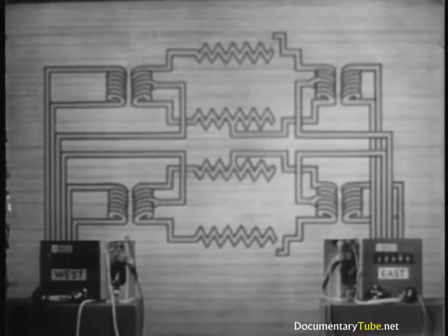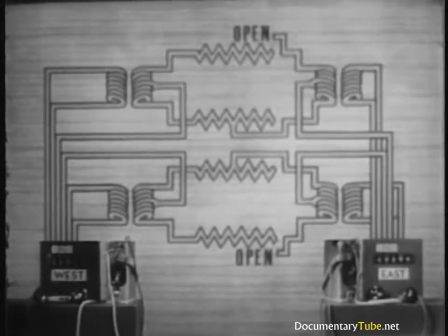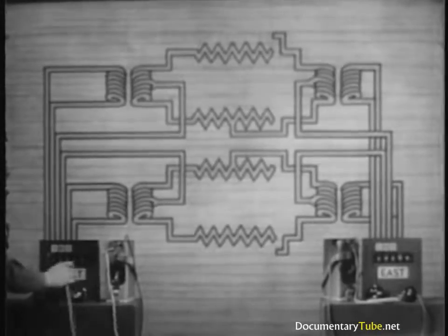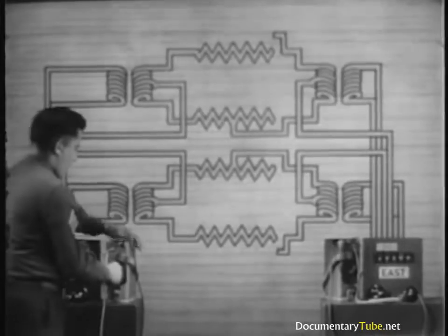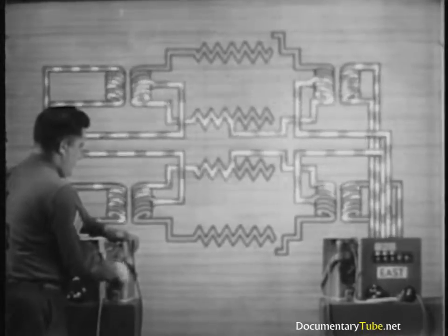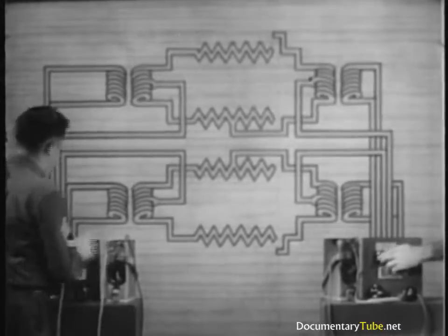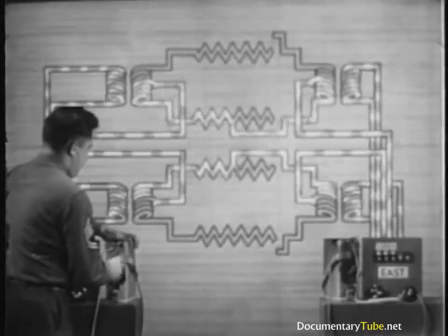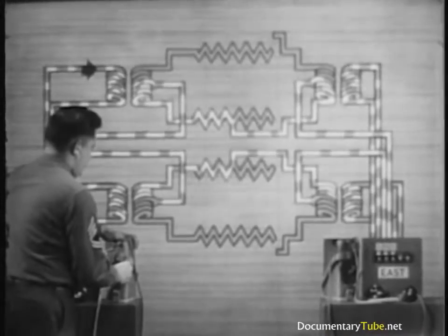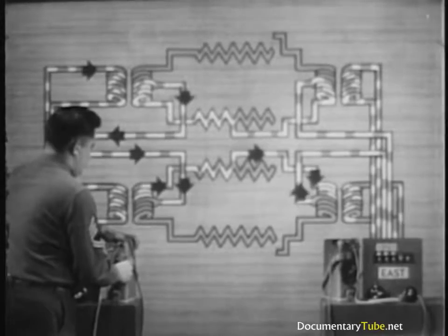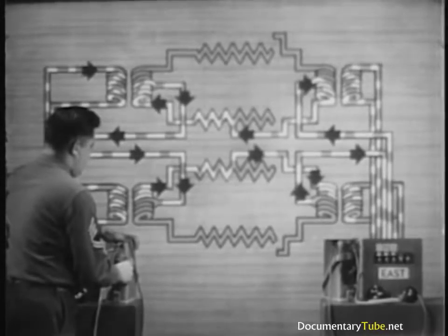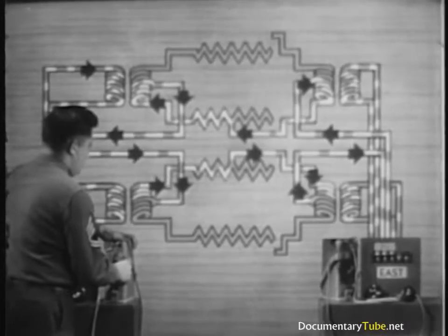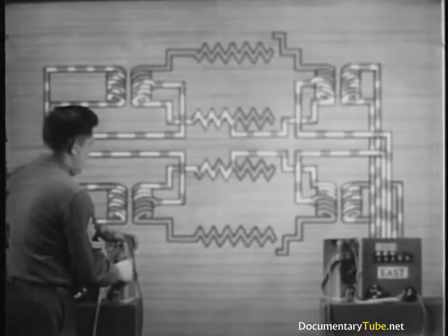What happens if both side circuits are open? This one's tricky, for now both sets of repeating coils are unbalanced. Ringing on either side circuit, we find that current flows through every possible drop in the phantom group. The jack we ring on is, in effect, connected in series to the other 5 drops. Either side circuit then interferes with both the phantom and the other side circuit.